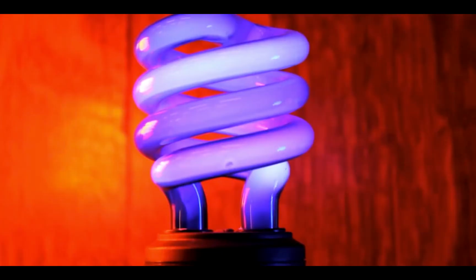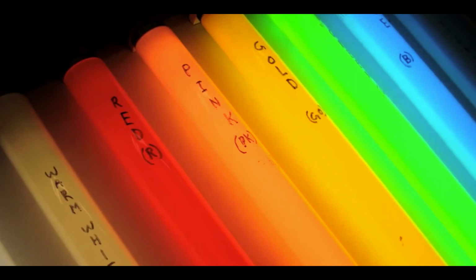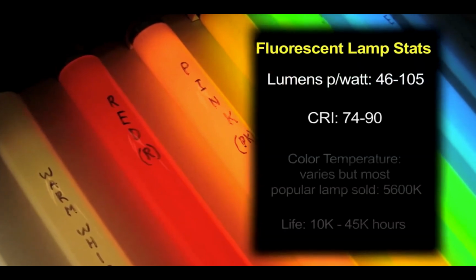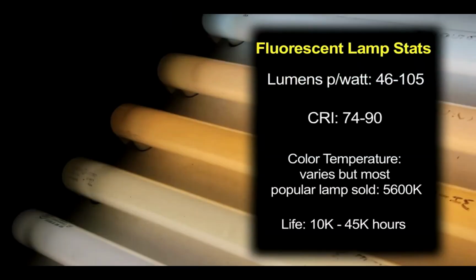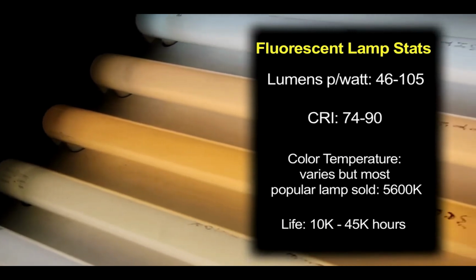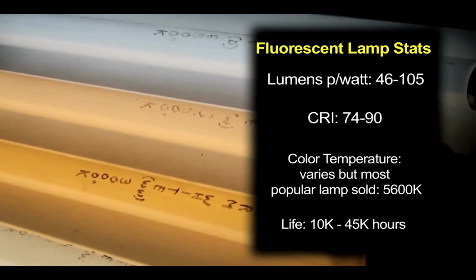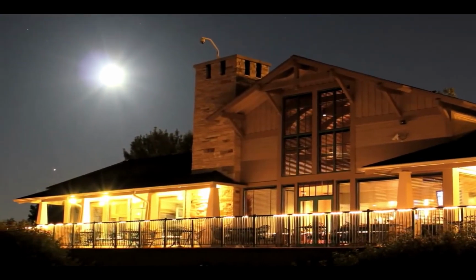The disadvantages are few. Maybe sometimes contact issues, they don't want to start sometimes, things like that. If you turn the lamp on and off frequently, it can shorten its life. The color quality of the light isn't as good as incandescent. That's another disadvantage. But otherwise, really their advantages outweigh their disadvantages.